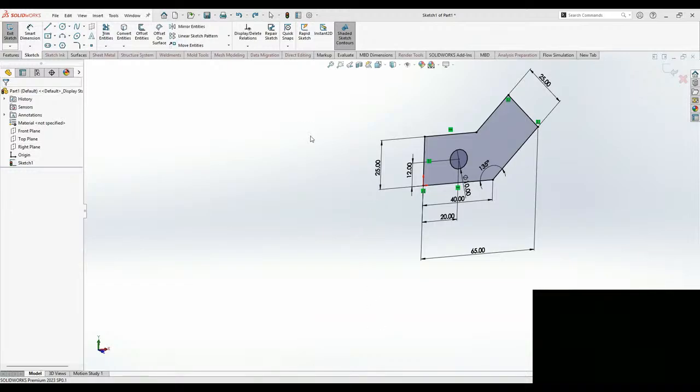Don't click OK yet. Let us set other shortcuts. For isometric, Control 7 is there. Sorry, my bad, there are no shortcuts assigned. Yeah, I for isometric is done. Now let's define the normal view. Here, normal to, I'd like to have it as N. Yeah, normal to view is done.